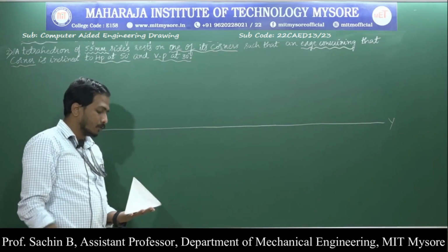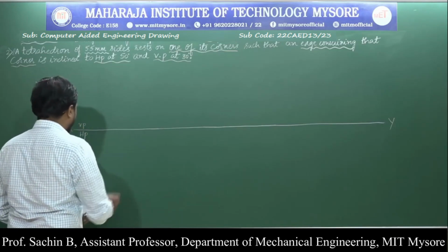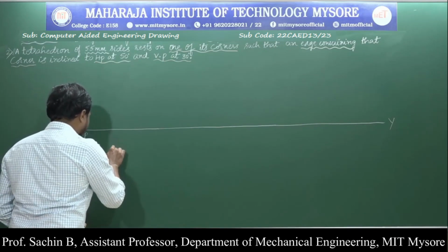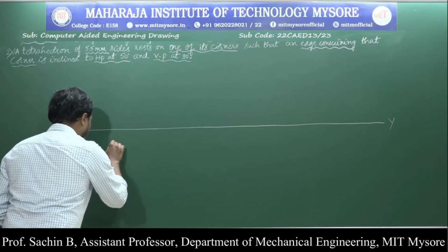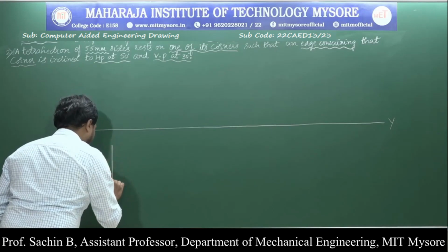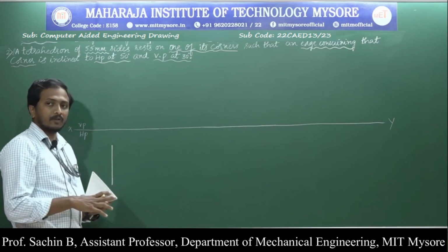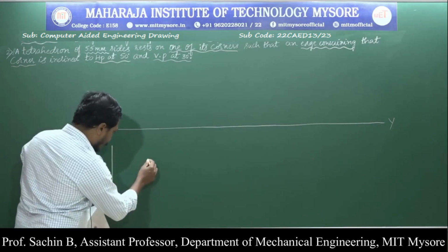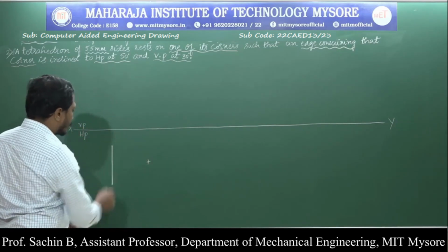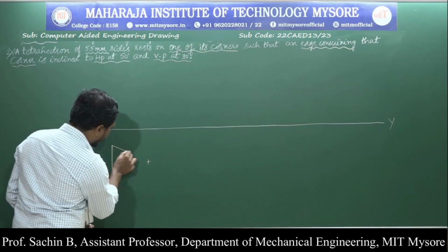If I look from the top view, the object will look like a triangle. First I will draw the dimension of 55 mm, a tetrahedron of edge length 55 mm. Next, with the help of the compass, I measure the 55 mm length. From this corner, I cut the arc. Again, from this corner, I intersect this arc. The 55 mm length edge I have written. Next, with the compass, I draw the arc. Next I will join them.